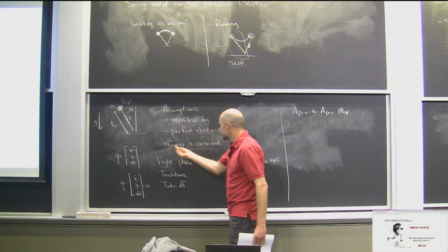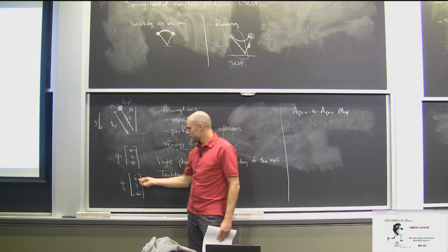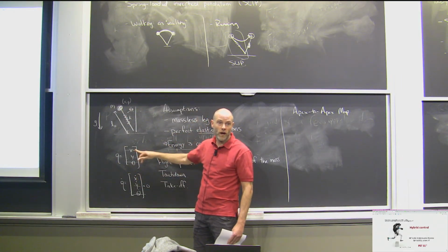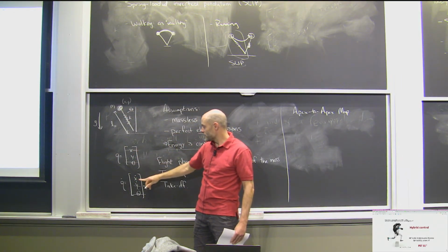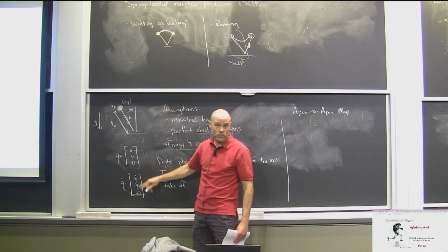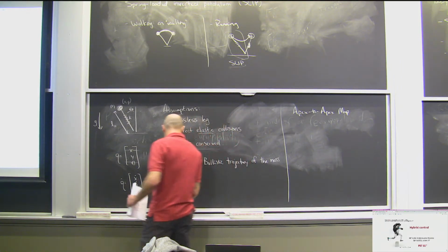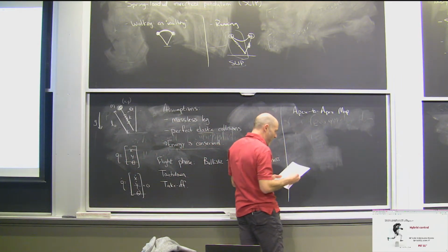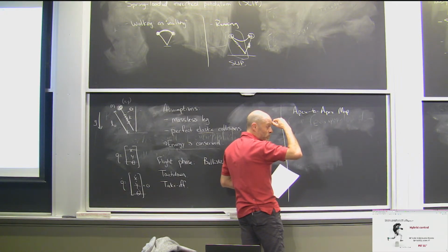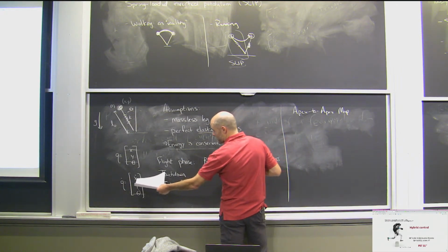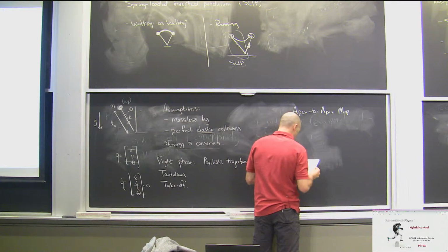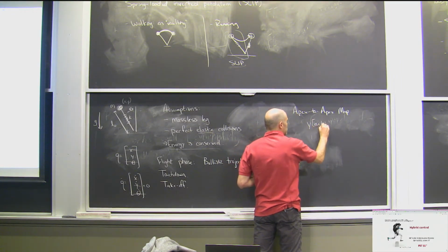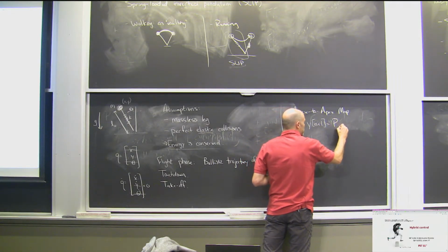If energy is always conserved, then when I'm just a ball flying through space, if I know x dot, then I know y. Or if I know y at the apex, I know x dot. Okay? So we'll do a map from y to y at the next step. You could similarly do x dot to x dot at the next step, but we'll do y, just a map from y n plus 1 through a Poincare map.